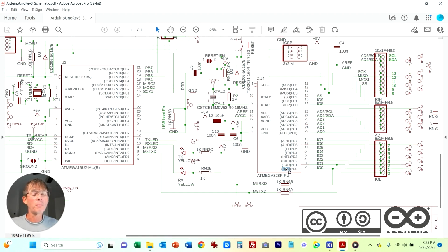So for our primary master controller, this is the receive line, and that's why they name this line RXD. But if you follow it up to this microcontroller, it actually goes to a TXD, the transmit line, even though they're calling it the receive line. I want to point that out because that can be a bit confusing at times. It's always best to name things from the perspective of the primary or master microcontroller.